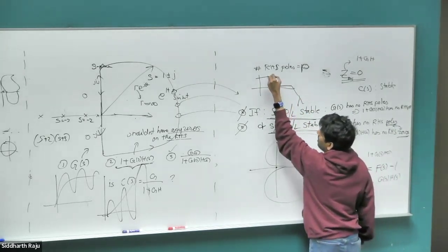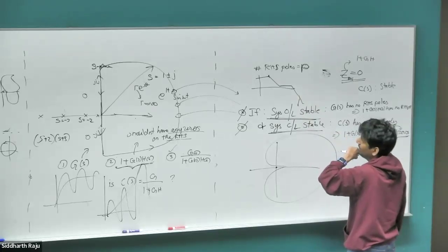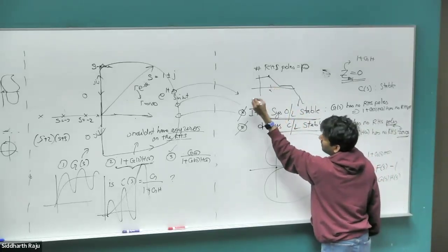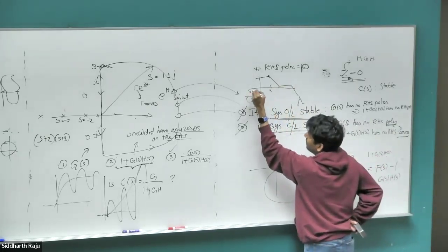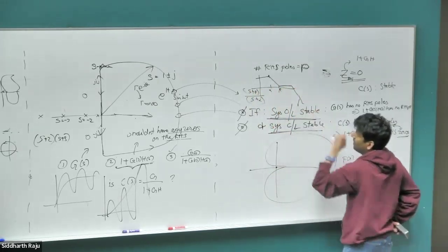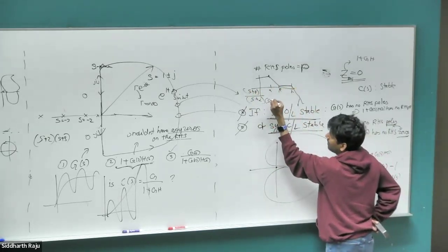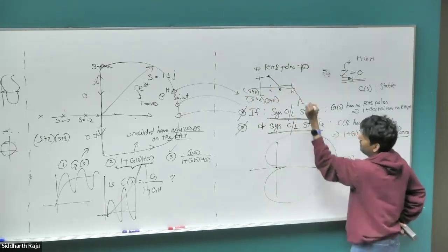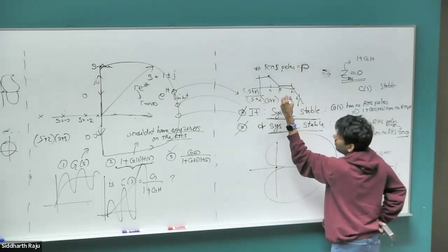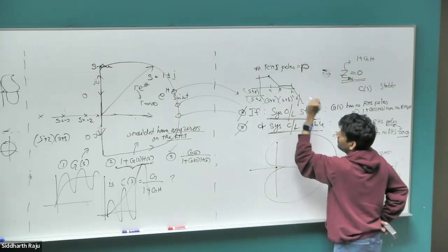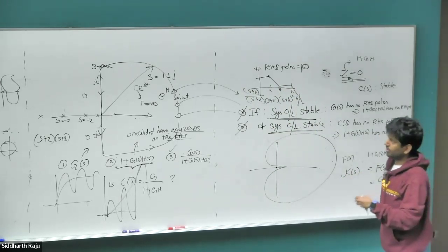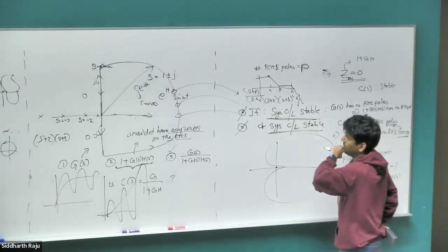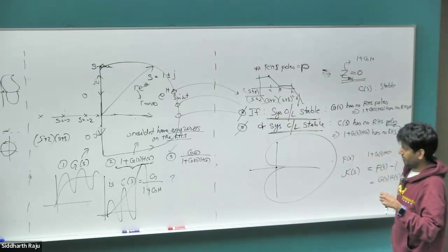So it has a pole here, and if it's going at 20 dB per decade, that's a first order pole. If this is alpha, I have a pole at alpha, and then here it becomes flat. So there must be a zero there, s plus beta, and then here again it's falling at some gamma, s plus gamma. And then here it starts to fall at 40 dB per decade, so that must be a double pole. It's pretty straightforward to tell just by looking at the frequency response what the poles of a system are. This is how typically you will get it for an industrial system. You pass different frequencies and figure out what the transfer function is. You don't typically have a nice mathematical expression.